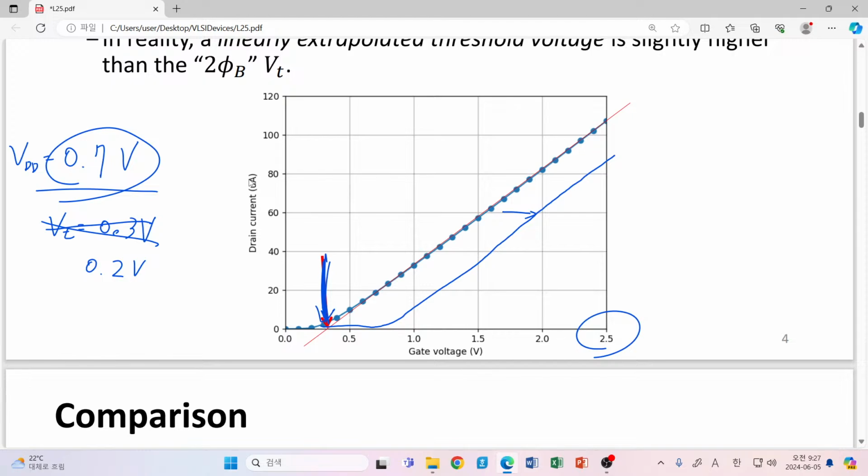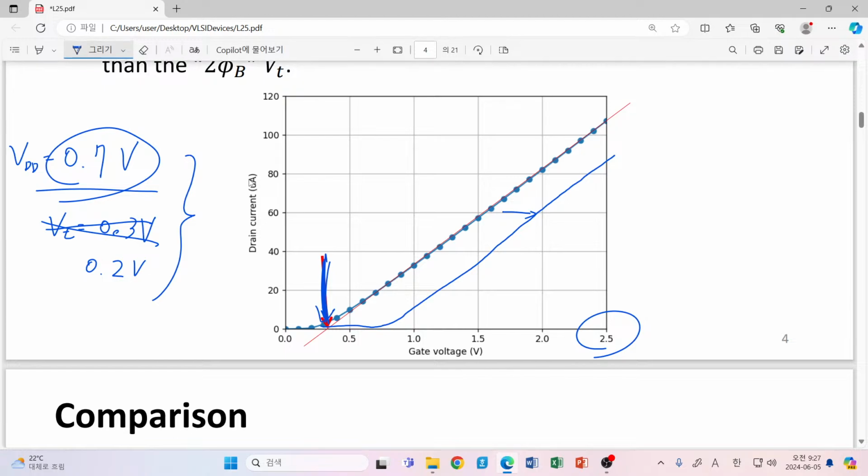There are two major components to determine your effective mobility, and one of them was doping density. If you intentionally increase your doping density, then your mobility value is drastically reduced by this higher doping density. So it is not that good an approach.